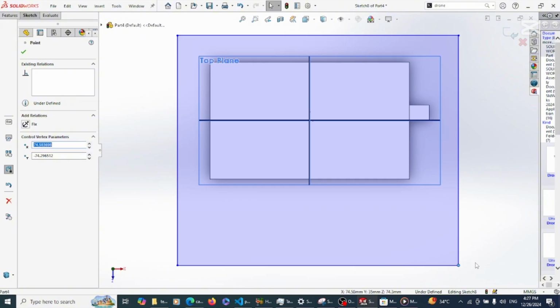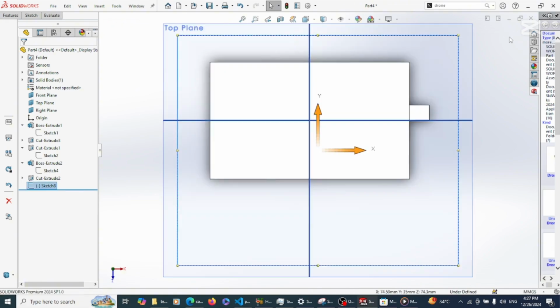But sometimes it doesn't work. What you do is that you exit the sketch. I told you that to exit the sketch, you click here. If you click here, it's going to discard the change. The last change I made was drawing the rectangle. So the rectangle will disappear. But if I click exit sketch, for example, and then I want to go back to edit sketch mode, I'll go to the last sketch which I just made. The last sketch will always be at the last place.